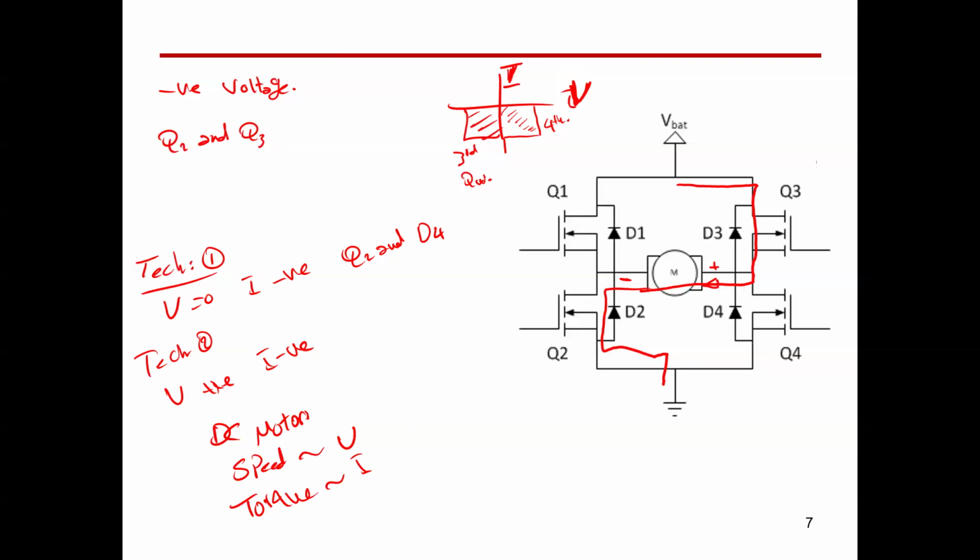So instead of having a motor, it will be a generator, and this can happen, for instance, in electric cars when you go uphill and downhill. When you go downhill, you don't need to provide any energy to the motor because you can already take the wheel motion and generate power and charge the battery during downhill roads. This is called regenerative braking.